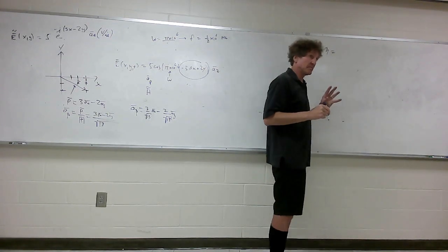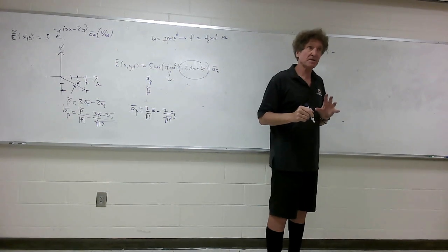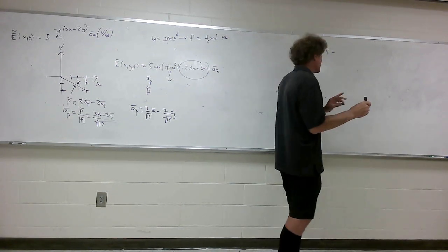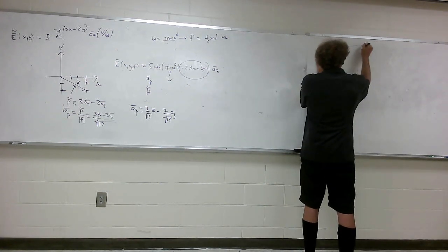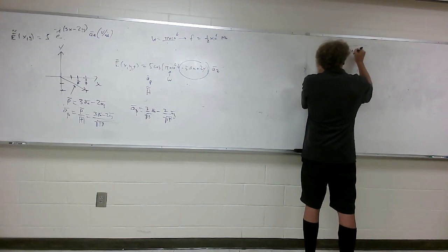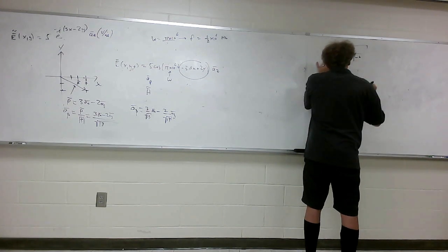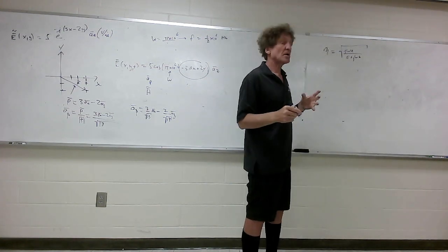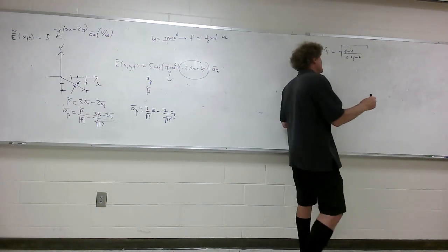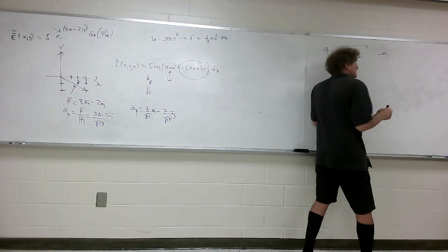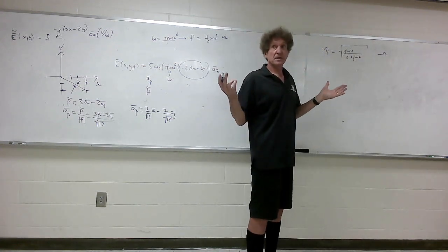This is the intrinsic impedance. Do you remember the symbol for intrinsic impedance, everyone? All right. That's equal to what? The square root of j omega mu over sigma plus j omega epsilon. That's always true for constant frequency. And the units of this are ohms. Just like the units of impedance always are ohms.